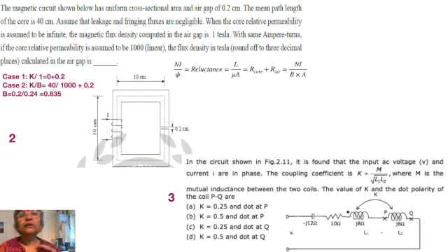So now there are two parts to the reluctance. One is what air offers, and the other is what the iron offers, because now it has reduced permeability. It does not have infinite permeability. So now the cause-effect relationship: Ni by phi, Ni remains the same. Phi is B into A, or flux density into area, which area also remains the same. It's only the flux density which changes.